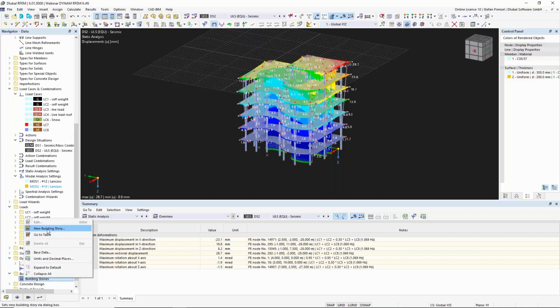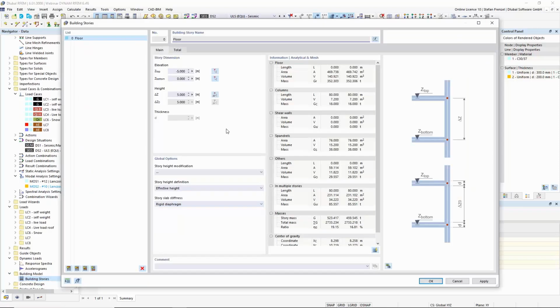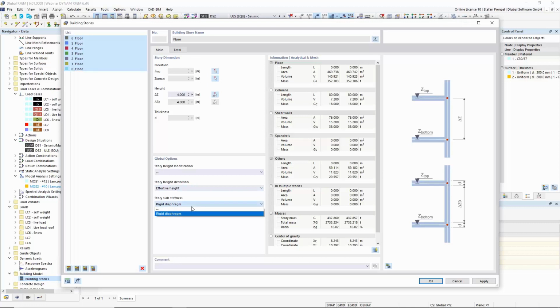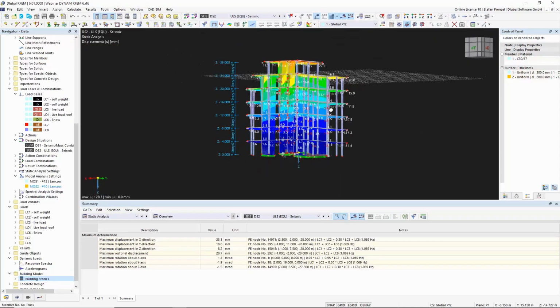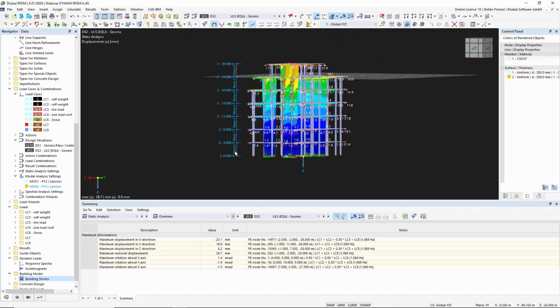That means for us, okay, we want to create a new one. My set top is -4, and here I want to create 6 floors without any diaphragm or something like this. You see, it's also possible to do a diaphragm calculation afterwards. But in our case, we created the whole structure with real floors, and therefore we don't need a rigid diaphragm for that. That's why I delete this one and go on OK. So the program now creates my 6 stories in this case.